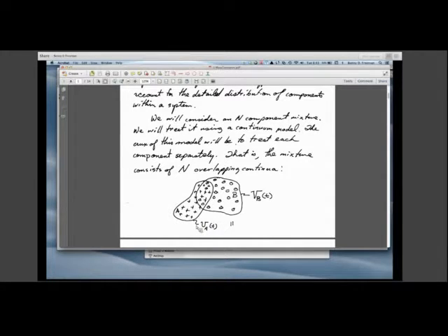As the molecules of A move or diffuse to regions outside the material volume, the shape and size of this material volume changes with time, so that it always encompasses each and every molecule of A. And there's no transport of A across the boundaries of the material volume for A. However, the other components, B, C, etc., are free to come and go as they wish in and through A's material volume.